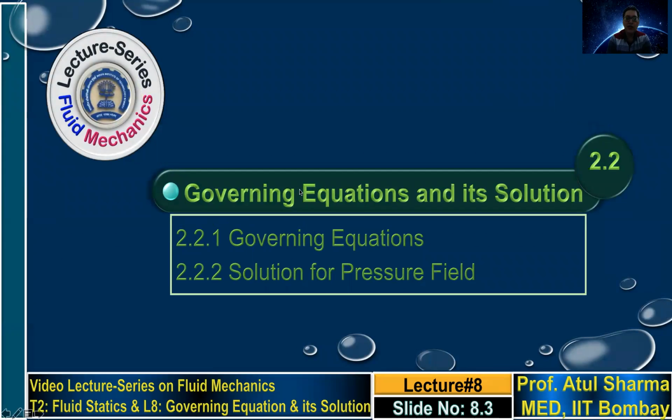The governing equation in fluid mechanics is a differential equation. We are starting here with fluid statics and later on we'll derive governing equations for fluid dynamics. So here the governing equation is presented for stationary fluid and later on we'll extend it to fluid in motion. However, for both the types of governing equation, the starting procedure is very similar, where we take an elemental control volume. Like if we are deriving in Cartesian coordinate system, let us suppose a 2D Cartesian coordinate system, then we take a rectangular control volume, a rectangular fluid element with delta x in the x direction and delta y in the y direction, and we basically apply certain conservation laws.